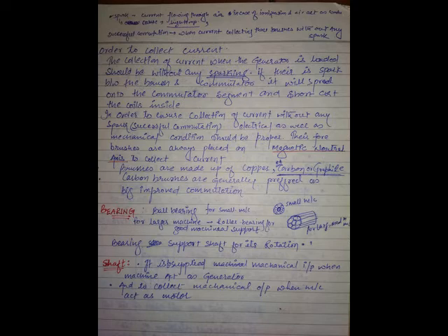You maintain in between 6 exactly. So place the coil sides in 1 and 7, or 2 and 8, or anything, but maintain exactly the pole pitch width. If you maintain, then what is produced in that coil? Maximum induced EMF.